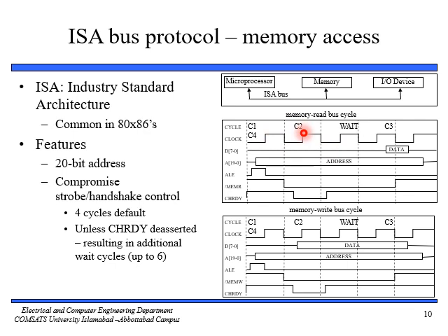In the second clock cycle, you can see, during the second clock cycle and third clock cycle, C2 and C3, the memory read signal sends a request for a read operation from the memory device. So we are going to read during C2 and C3, from the memory.